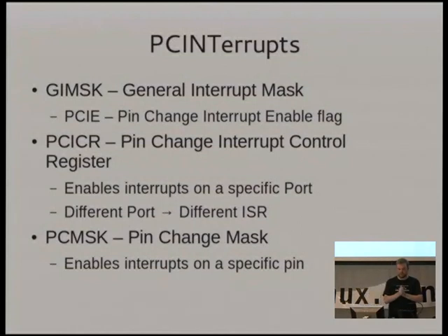The earlier that the chip can decide not to deal with an interrupt, the less power and the less effort the chip is going to use not dealing with that interrupt. So if you have a whole bunch of things, buttons say, that might cause interrupts, and you group them all on the same port, that means you can turn off all the interrupt handling for the other ports. So there's no monitoring of that at all while the chip's in a sleep state.